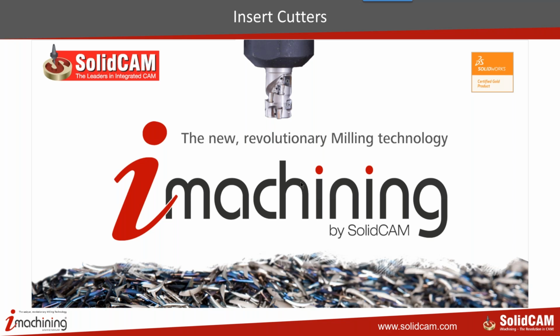iMachining does that using proprietary knowledge-based algorithms that consider the material's characteristic behavior during a cut, the various geometric and mechanical properties of the cutting tool, and the machine's rigidity and capabilities. It considers all these things and calculates the optimal cutting speed and radial depth of cut for a planned cut of the desired axial depth.